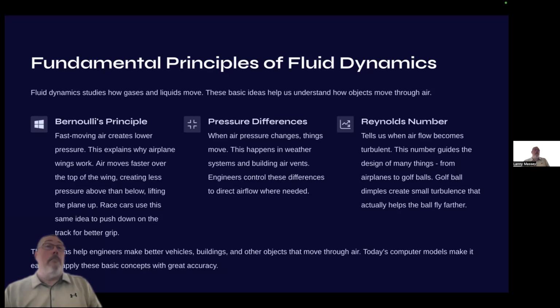Part of that is when another car gets right in behind them, it can cause some lift on the back end of the car in front by air turbulence. It causes the air to spin, and then that air gets up underneath the car in front, lifting. Well, it isn't lifting, but it is, but it isn't. It's causing less pressure on the ground, and therefore that car in front starts losing some traction, and that's what they're talking about when they start getting squirrely in the back end.